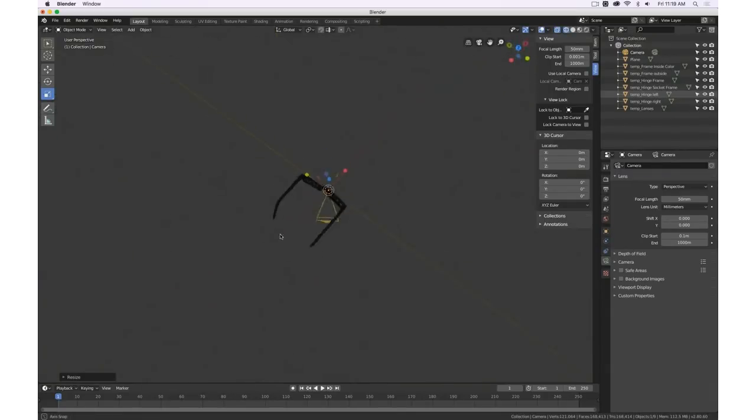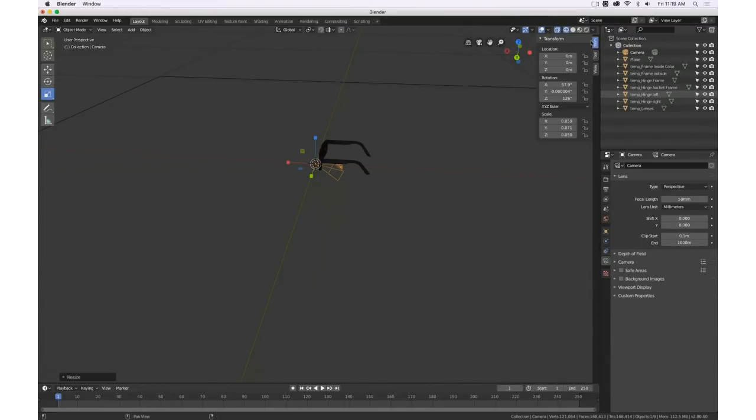And this camera has a bad position and a crazy rotation. So on the right side, when you go to items, see transform, and there it tells me this camera is rotated by these degrees. So I can click and press 0, click, press 0, click, press 0, and everything is fixed. Very nice. So also here I can click and drag.